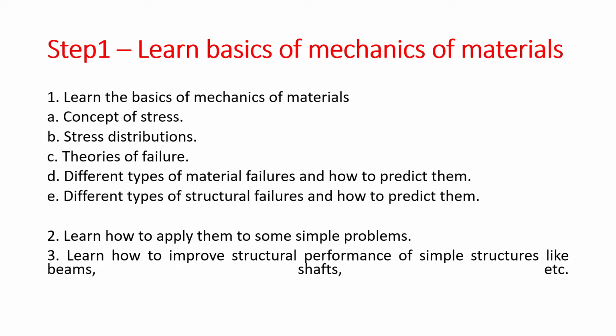Step one will be to learn the basics of mechanics of materials. Mechanics of materials includes strength of materials, theory of elasticity, and other sister sciences. Basically, what you have to learn in this is the concept of stress, stress distributions, theories of failure, different types of material failures and how to predict them, then different types of structural failures and how to predict them.